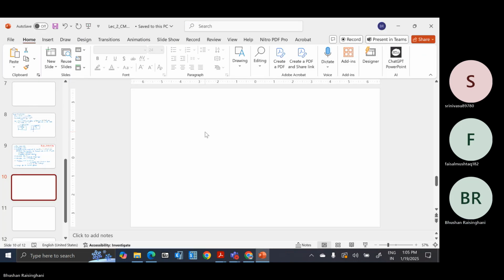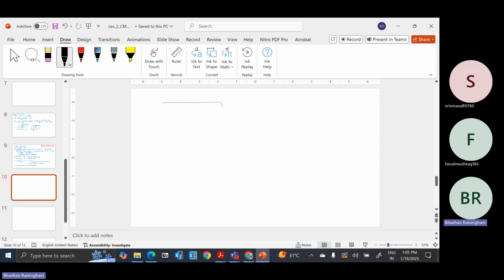That way I can estimate the forces. If I show you here in this particular arrangement, if this is the building and this is the shear wall and this is my CR, then there will be a distance and there will be a stiffness. So I call it R, I call it K. Then there is a wall like this here or here, so I make it 1, 2, 3, 4.